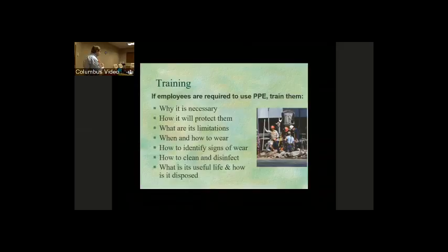Safety glasses, for example, are impact resistant, but they're not good for dust. They're not good for mist or vapors. So they're good for impact. That means if you have a nail fired 6 inches from your eye with a 100 PSI air nail gun, those safety glasses will stop that nail. They are pretty impressive. They are impact resistant. They meet the ANSI standard Z87 for the hardness of those glasses.